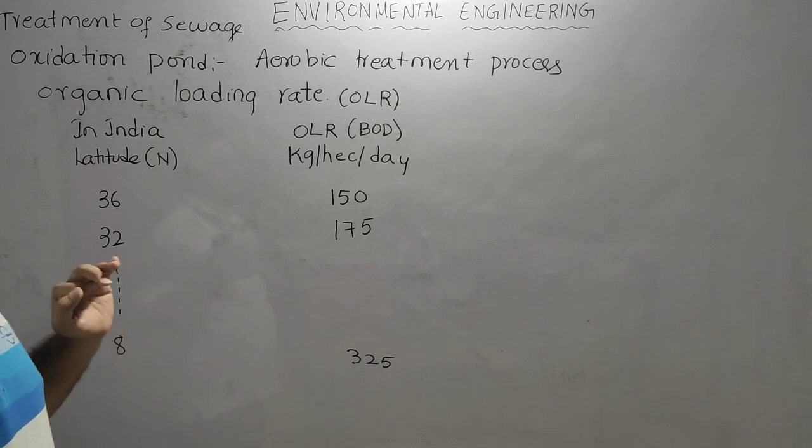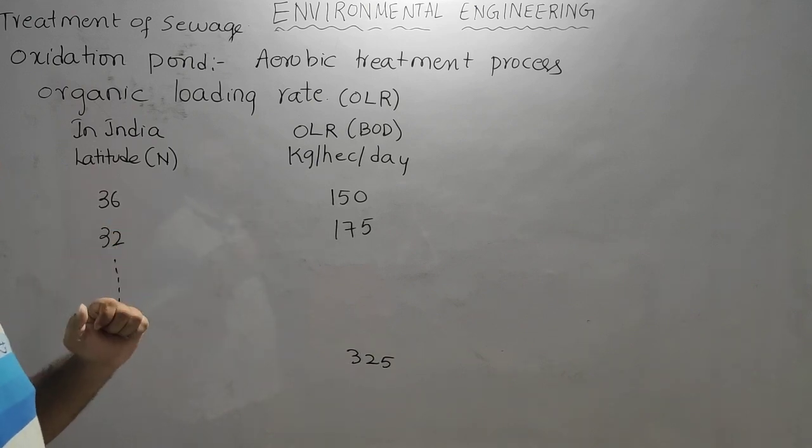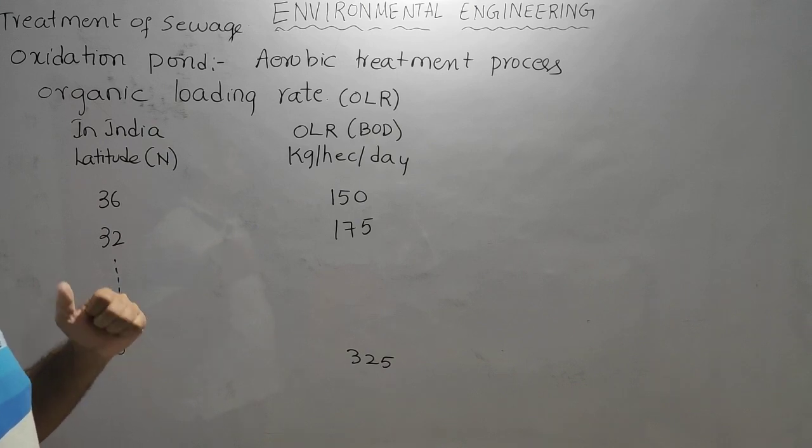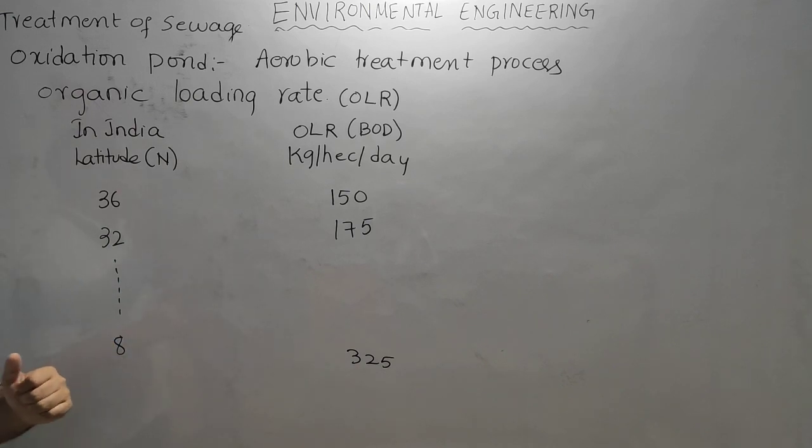Now, how many days are you giving the tank as detention time for the decomposition process to complete? Depending on that, we can design the oxidation pond.